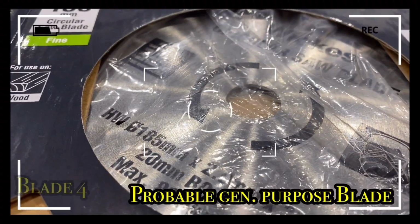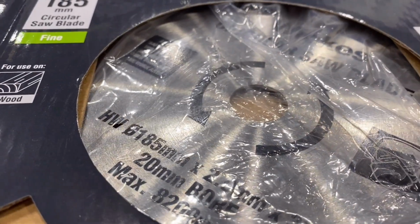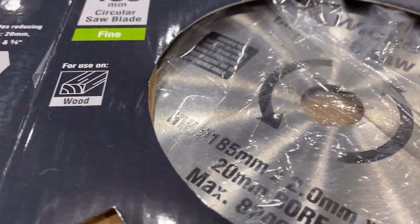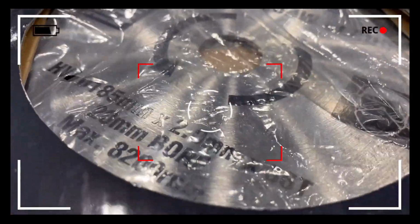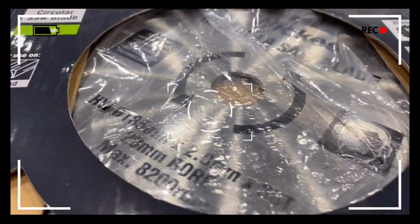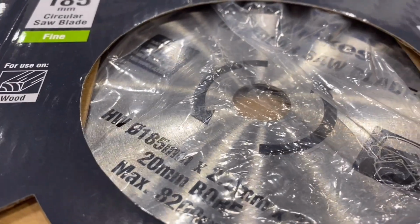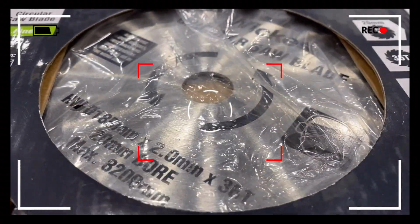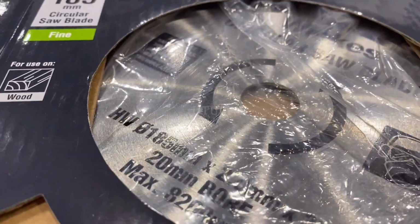The next blade's rim size is 185mm or 7.25 inches. It's got a 2mm kerf and a 20mm bore. It's got 36 teeth, which means it's got more teeth than your conventional 24T ripping blade. And the gullet here would be a lot smaller. And again, it's closer to the lower limit threshold for combination or general purpose blades. So this blade should give fast cuts, and can be used for medium ripping and cross cutting. And you should have a more refined, less coarse cut finish.